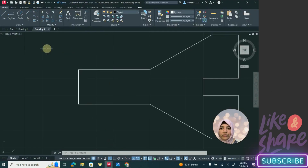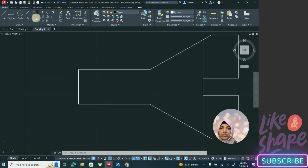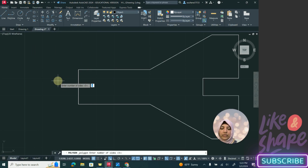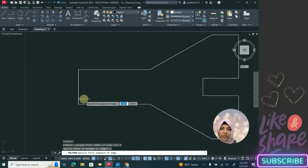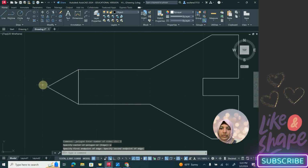Okay, so for the nose cone, there is a polygon command that you're going to use, and it's under rectangle. Usually you will see rectangle and click on the arrow next to it, and you will click on polygon. So polygon, you're going to assign a number of sides, 3, and then you're going to type edge for E, and then click and click on the other endpoint, and you will have the cone.